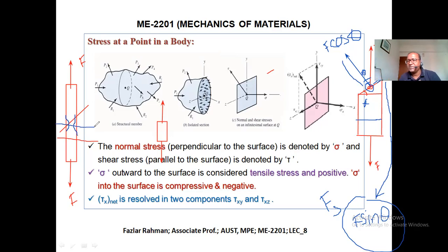That means it is shear, right? So even though you are pulling, at some point the material experiences shear force or shear stress. That's why it splits into two parts. And we get this maximum shear force when the angle is 45 degrees.